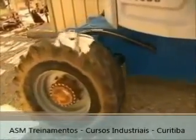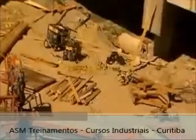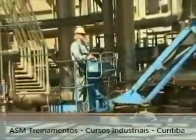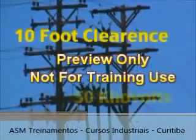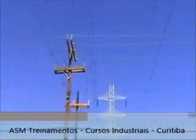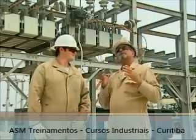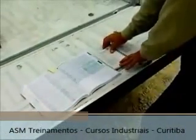Hazards that may create dangerous driving conditions, such as overhead power lines, holes, drop-offs, bumps, lumber, tools, and debris, must be identified, and procedures to avoid any hazards made known to all employees. OSHA requires personnel to maintain at least a 10-foot clearance of all power lines with less than 50 kilovolts. If a power line has more than 50 kilovolts, additional distance is required. Employees should consult with their supervisor to determine the proper distance needed. Electricians have different guidelines and should consult with their employers concerning this issue.